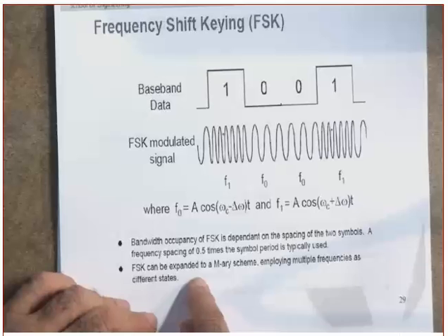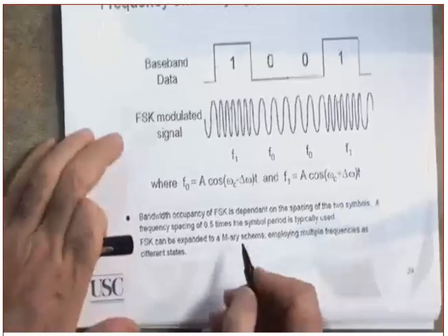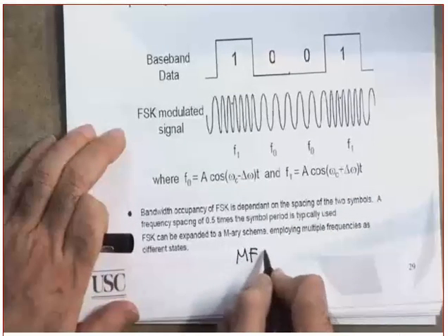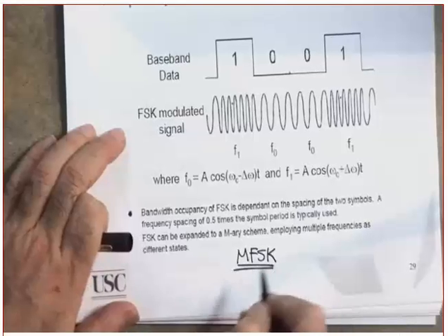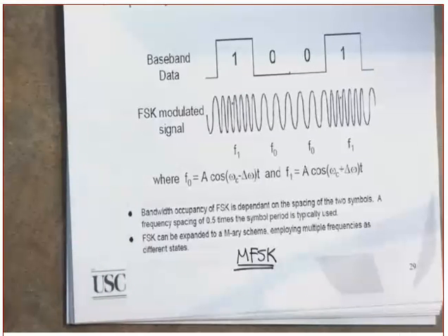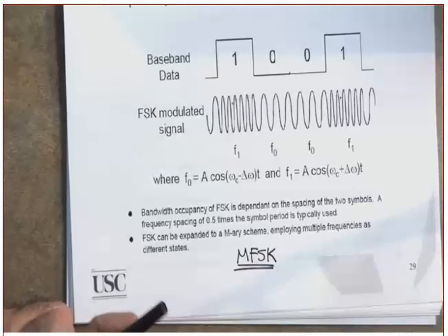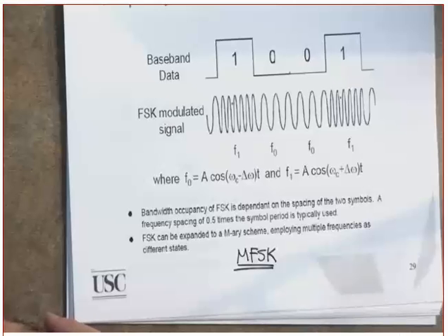Frequency shift keying can also be expanded to an M-ary version. In other words, we call it MFSK. Okay, is this bandwidth efficient or bandwidth inefficient, the MFSK? You are guessing? Will the bandwidth increase in MFSK? You are using multiple frequencies. Will the bandwidth increase? And the bandwidth will increase.